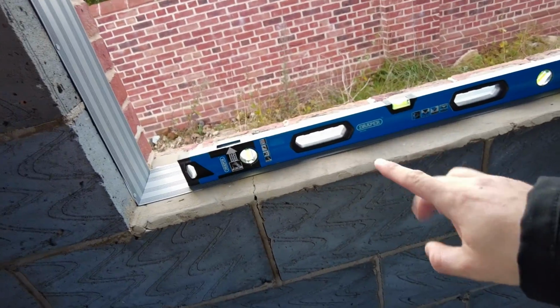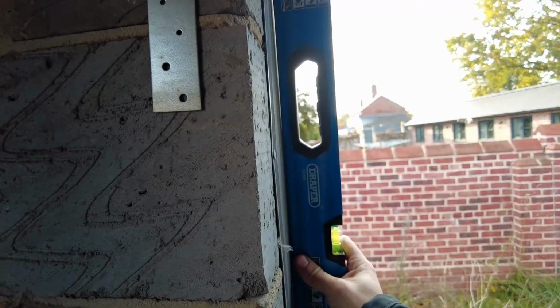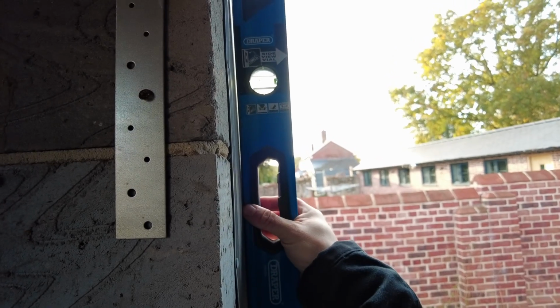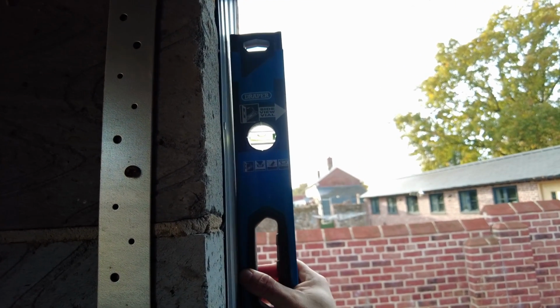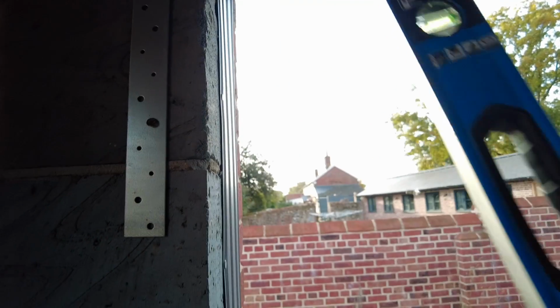But I use a level. And what you want to do, check all sides, make sure it's pretty much there. You want to go vertical and plumb, and then as long as your side is no more than 5mm off plumb or level, you're pretty much going to be all right. Now, if they are massively off level and plumb, especially over a long distance, then you might have to deduct a little bit more than the 5 or 10mm.